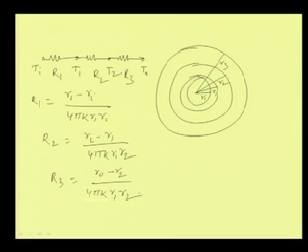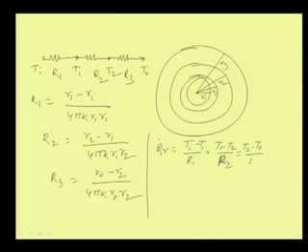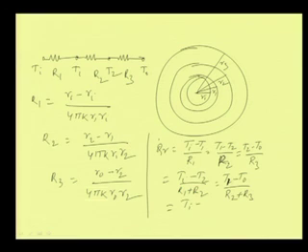So, these are the resistances, and we can also find Q dot, as we have discussed previously, from (T I minus T 1) by R 1, which is equal to (T 1 minus T 2) by R 2, which is equal to (T 2 minus T 0) by R 3, which is equal to (T I minus T 2) by (R 1 plus R 2), which is equal to (T 1 minus T 0) by (R 2 plus R 3), and this is equal to (T I minus T 0) by (R 1 plus R 2 plus R 3).